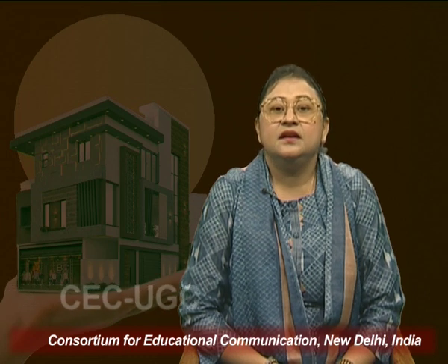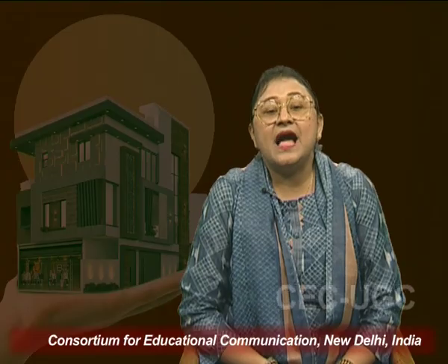User needs and characteristics should also be taken care of. For example, as we discussed in the second lecture on anthropometry, the heights, levels and sizes vary depending upon the user needs. So, in a children's library, the shelf height would be much lower than the shelf height of an adult or grown up library. The accessibility and the safety all need to be taken care of. Impacts on size and layout: occupancy and user needs directly influence dimension, circulation and spatial organization.